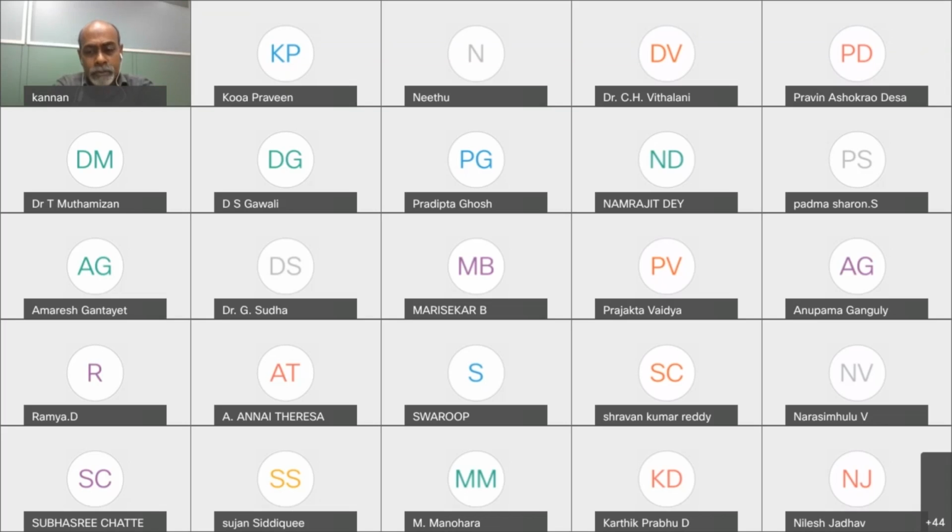All the BLDC motors, you can use only MTPA. In all the SPM PMSM motors, what is called SPM? Do any of you know? If you have seen the lectures, you will know. It is called surface permanent magnet. In all the surface permanent magnet motors, which means the magnets are pasted on the surface of the rotor, in all motors of that type, you can only use the MTPA algorithm.